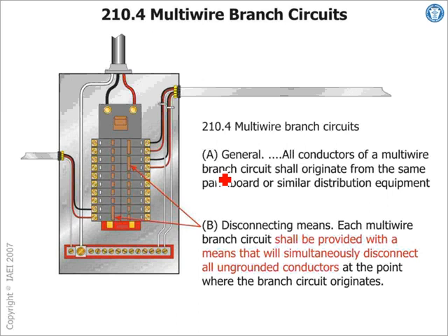So the only time you have to clarify them is if you have different voltages. We're talking about like you have 480, 277, 208, 120 panels, and you have them entering the same box, gutter, or so forth. Then you have to use a different color-coded neutral. Is that what you're saying? That's what I've heard. Yeah, if your building has two voltages like 480, 277, 208, 120, then you have to identify the phases, every system by phase and by system. So you have to color code the systems basically for feeders and branch circuits.